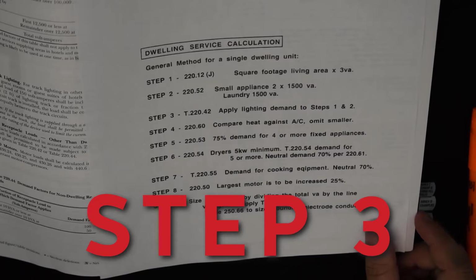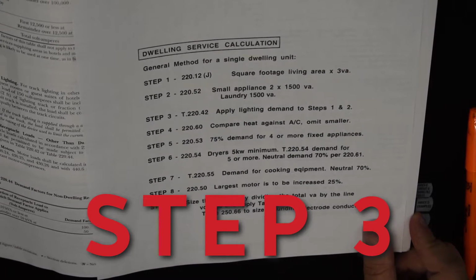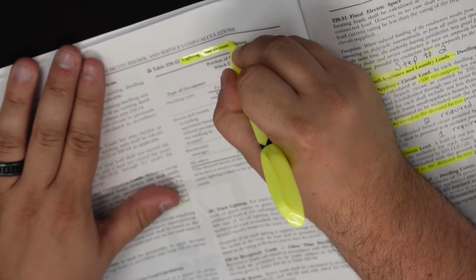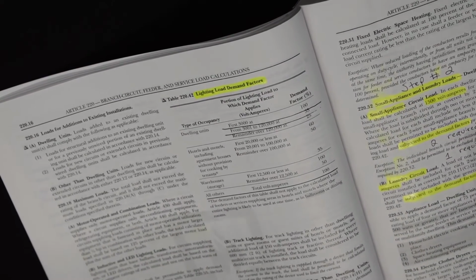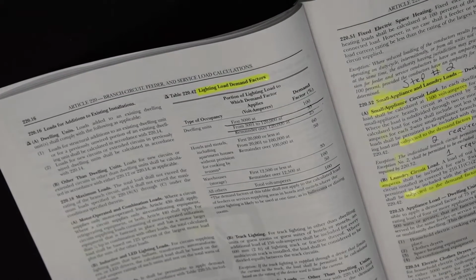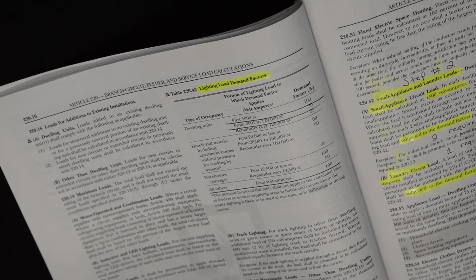Step 3 says Table 220.42 says apply lighting demands to steps 1 and 2. Okay, so we're going to go to this 220.42, lighting load demand factors. Now this table tells us for dwelling units, the type of occupancy, the first 3,000 is at 100, that's percent. And then from 3,001 to 120,000, we're at 35, and that's percent.